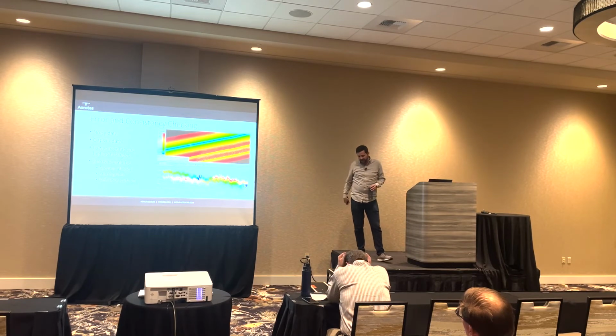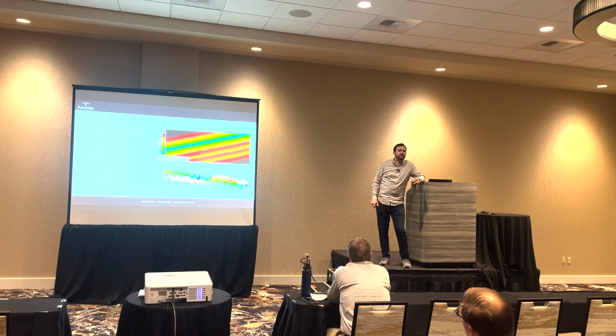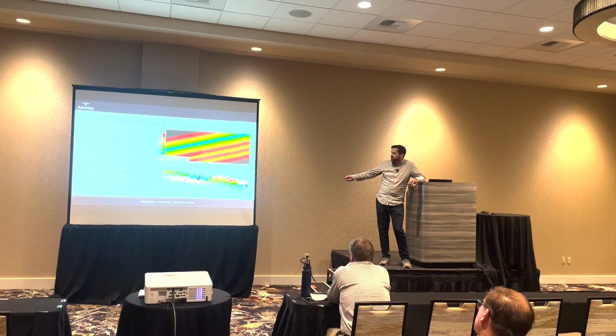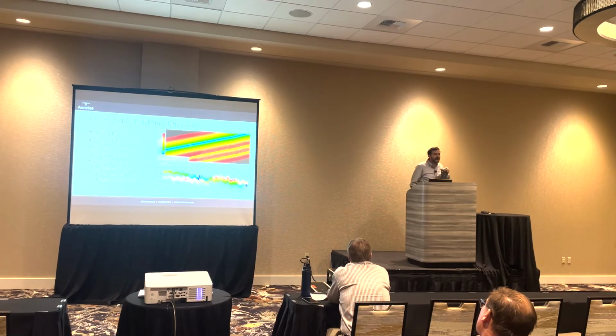I've said that some software, including DJI Terra, has some really black-boxy stuff. They have a checkbox when you're creating the point cloud for optimized point cloud accuracy, if anyone's familiar with that. We've tried using it, and what that occasionally does is force these two swaths to line up with one another, but it does it in a really dumb way. We've done it with a lot of ground truth data and check shots, and oftentimes it'll take the correct data and bring it down to the incorrect data so that it gives you bad data. Their documentation on it is atrocious, so we don't actually know what it's doing in the back, but we know that it doesn't produce reliably good results.